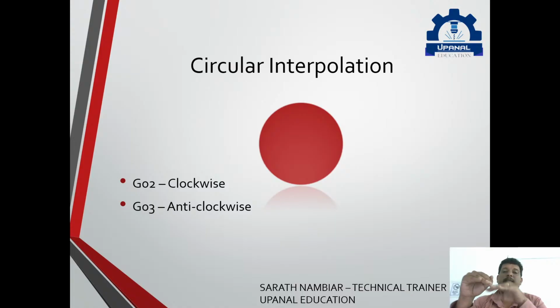So when it comes to the corners, sometimes, for example, if you have a radius like this, from here it will come in G01. Now when it turns, when it has to take a radius, this is the clockwise direction, we will use the G02 option to tell it to go in the clockwise direction at this radius. We'll give the radius.